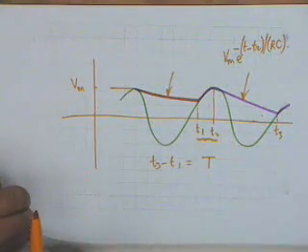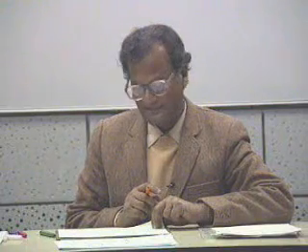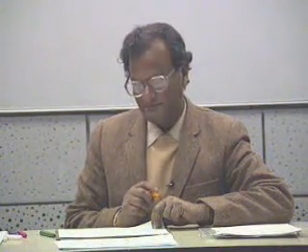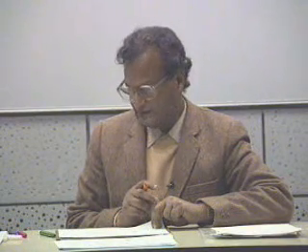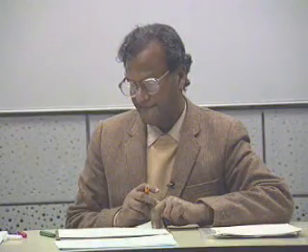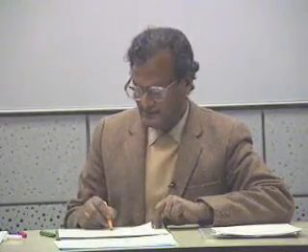So what do you get in the decay of the voltage that is due to the capacitor? Across the capacitor, at t equal to T2, the value is Vm, and then it decays. Similarly, you could write for this part. You have to have a prime somewhere, the initial value of the time. But do you understand this point? That the difference between T3 and T1 is exactly equal to 1 time period.